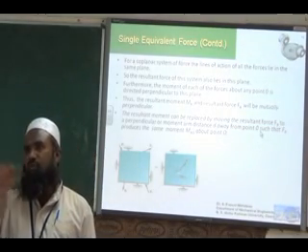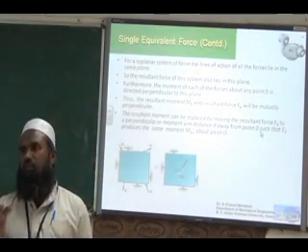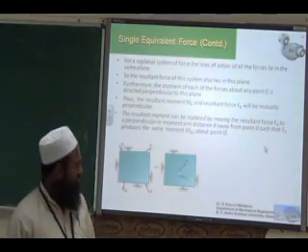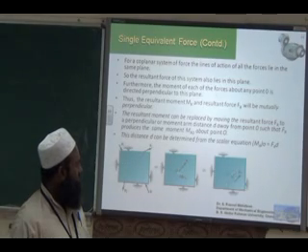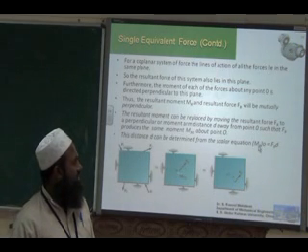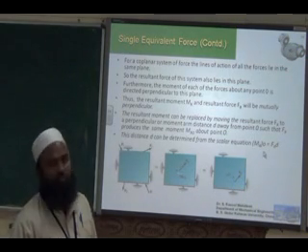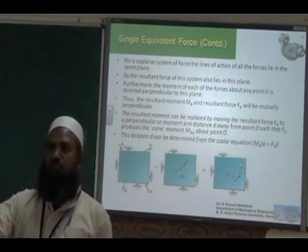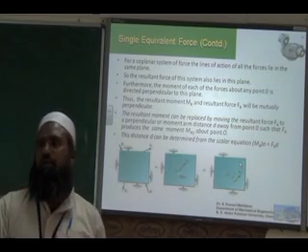That is the distance to which we have to move the force so that it compensates the moment which we have. So we move it to a distance D. D can be obtained from the equation: resultant moment about O, MRO, divided by Fr will give you the distance D. So we convert all the forces and moment to a single equivalent force.